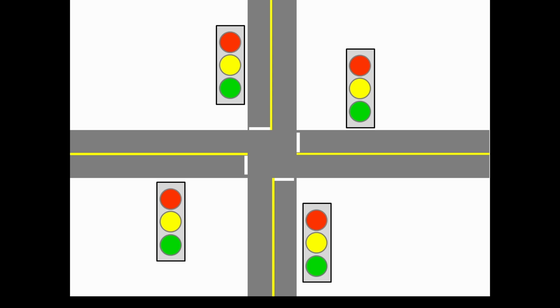We talked about feedback control systems. We talked about the basics of those and how they work. This is yet another way to control real-world electrical equipment. And to understand state machines, we are using this very simple example that you see here that you're probably familiar with, and that is the control system to control traffic lights at an intersection.